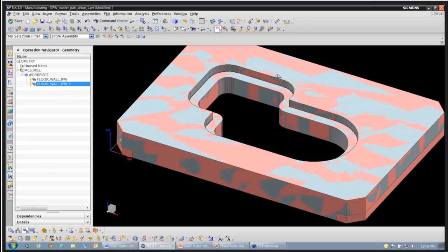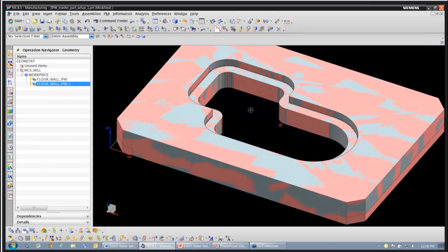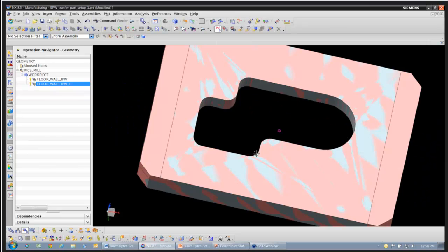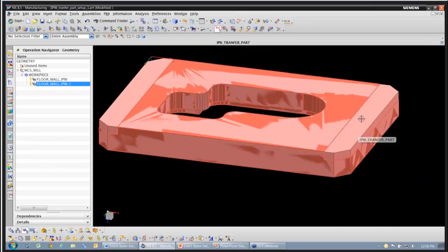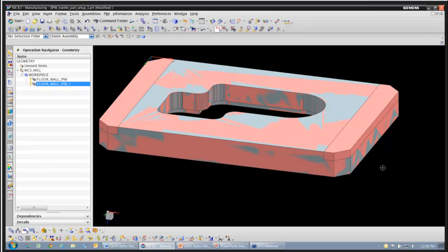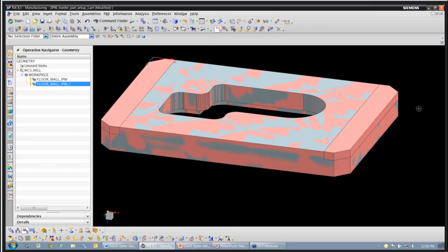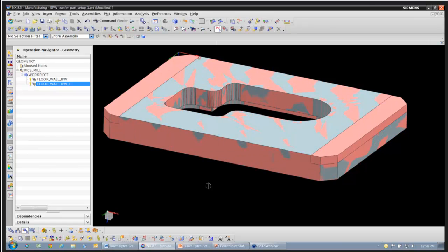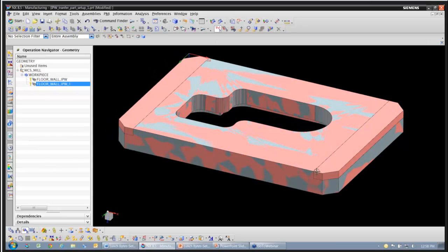and you can see that this step shape on this cutout has already been done. These chamfers on the outside have already been done, and this cutout has already been cut all the way through the part. If we flip this over, we can see there's a couple step shapes on the outside of this plate. And by looking at our existing IPW, these haven't been cut. So we're going to reference this IPW from set 1 and reference that onto set 2.